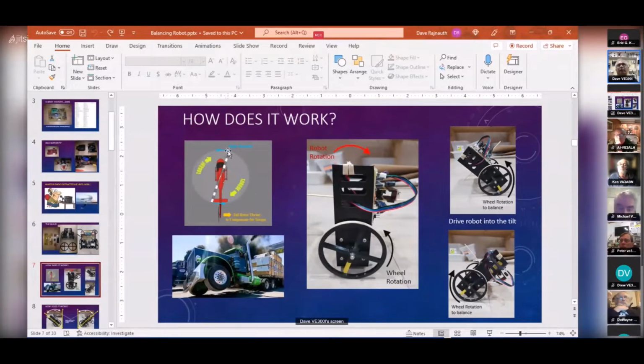Because the blade is turning this way, the body of the helicopter wants to turn the other way. If you turn the blade this way, the body wants to go this way. That's why you need to have a tail rotor, and the tail rotor balances out that torque.